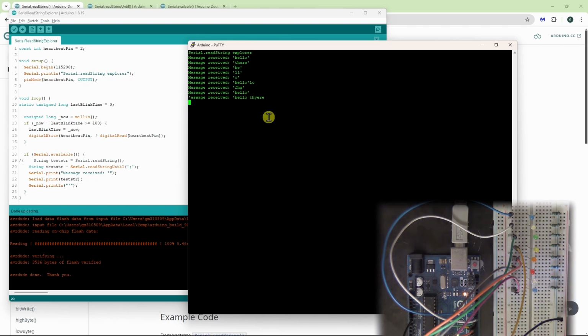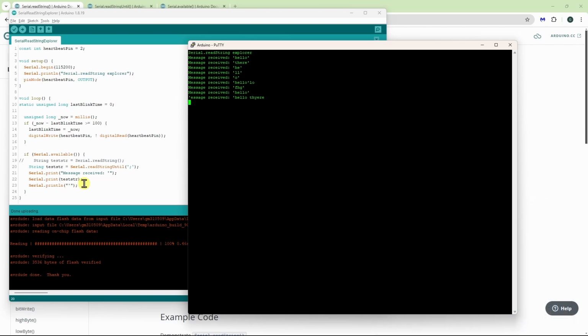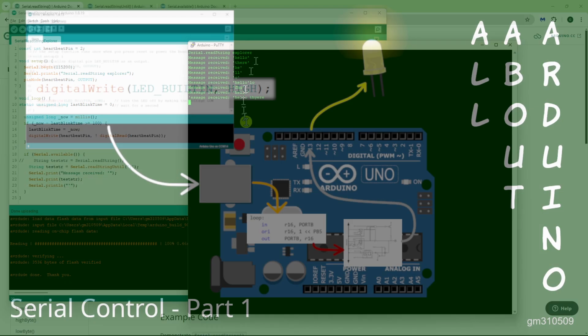So if you were only ever going to use the Arduino IDE, this is fine. If you're only ever going to use the one string, then this is fine as well. But if you're starting to do more complicated things like string concatenation and creating your own string variables and using other packages that use strings or dynamic memory allocation, you could eventually start getting some problems with, as I mentioned before, I won't go into the details of it. That can be the subject of another video if you're interested. But memory fragmentation could lead to random system behavior and crashes and all sorts of undesirable behavior.